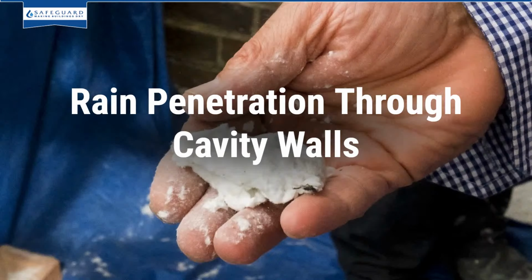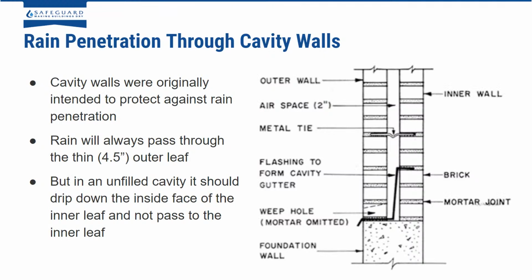So we're just going to now look at cavity walls to finish off, I think. So where does rainwater become a problem? Cavity walls were initially designed as a way of protecting against rain penetration. That was their primary function, and the idea is rain would always pass through the outer leaf, as a single skin brick wall will never stop rain penetration. So that's why you have two skins, and the idea is that the water drips down into the cavity drains and through a weep hole, and the moisture is emitted.